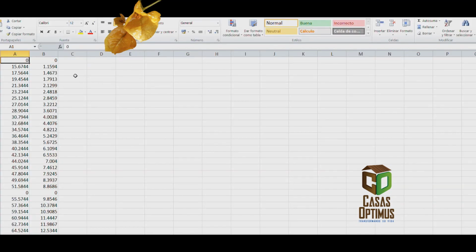If you use a spreadsheet from a professional program, in some cases it can come out without the comma in the middle of the numbers. Then you will have to concatenate all the coordinates. It's simple. Put the pointer in C1 and put the concatenate function. You must specify cells A1 and B1. Also put the comma that will separate the numbers. You click accept and that's it. Copy and paste and finish your work fast. A little reminder, the concatenate function may vary from program to program.